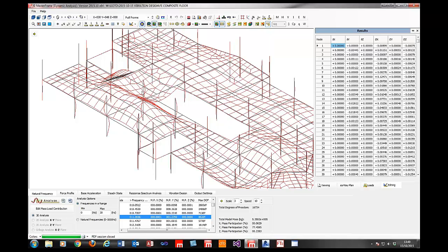Now what that effectively means is the structure here and its natural frequency is much stiffer than the actual walking frequency, and as such the way the walking activity interacts with the structure is different. It never actually develops a steady state sinusoidal type movement, but rather it manifests in a series of high accelerations which correspond to each heel strike and then dissipate off quite rapidly. And in that instance, it's recommended that we measure the response in a slightly different way.